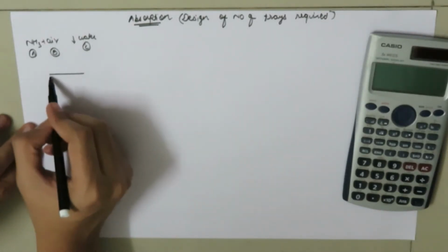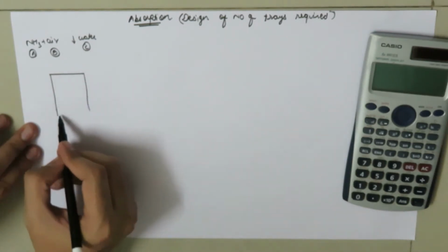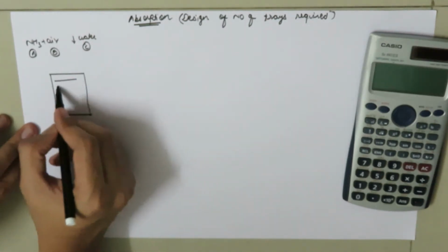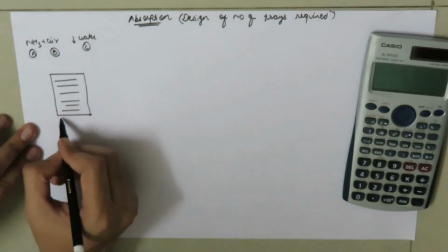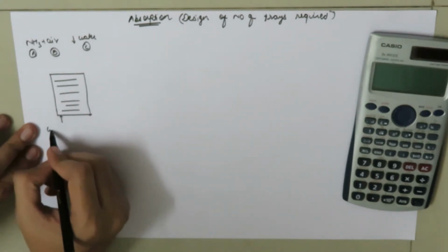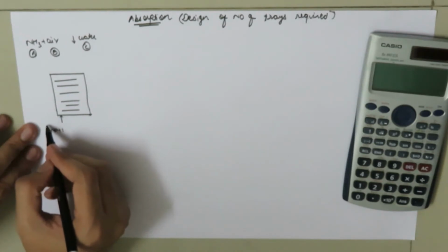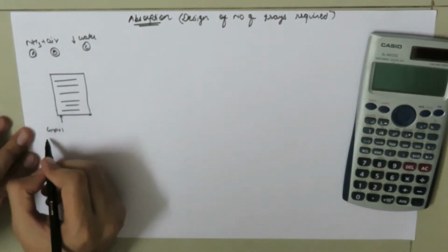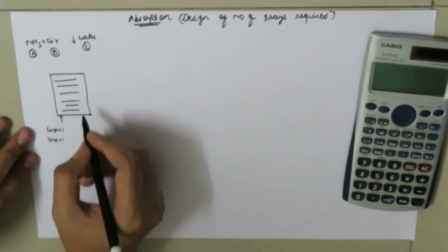So if you draw the diagram of this absorption tower, and we are going to deal with the designing of the number of trays, if we represent the trays like this, this will be G_{N_P+1}, the total amount of gas mixture entering the absorption tower, with mole fraction Y_{N_P+1} of ammonia.